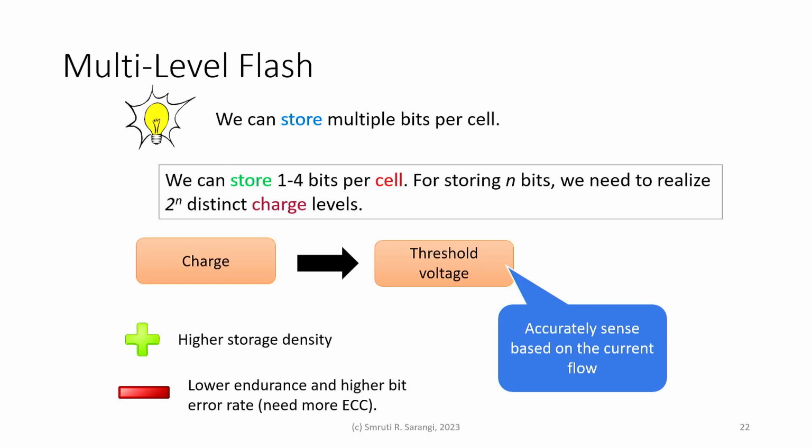We could also have, or maybe as an option have, multi-level flash, where we can store multiple bits per cell. Not necessary to store one bit, but let's say we can have 4 different levels, in the sense that in this case we have several threshold values. So then we can have several ways of enabling a cell by putting it in different zones and seeing whether it is conducting or not, right? Or we can see even how much it is conducting. So conducting is not a 0-1 thing. We can treat a transistor as an analog circuit and we can see how much current it is conducting.